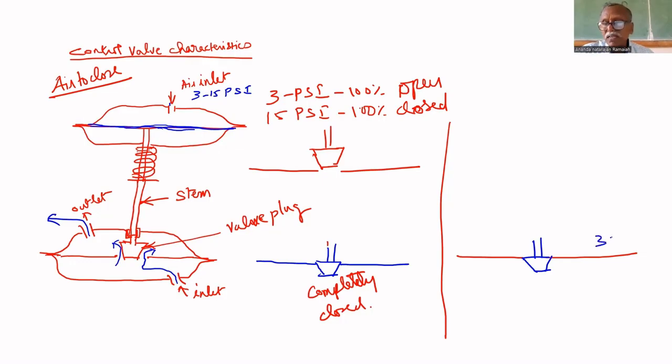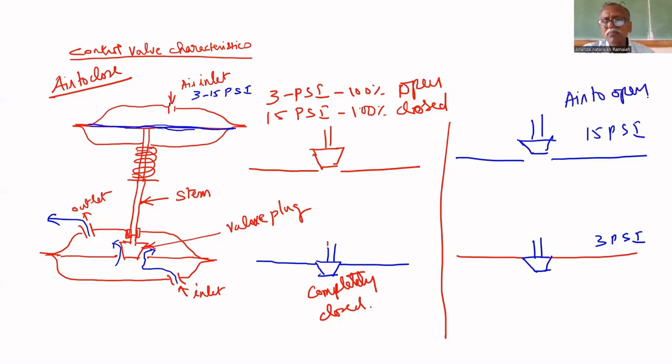This is the position for 3 psi. This is the position for 15 psi. This is air to open.